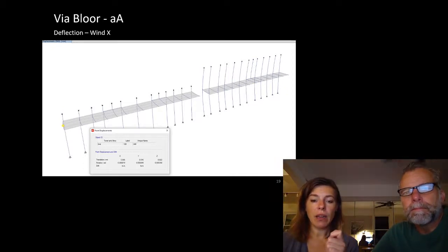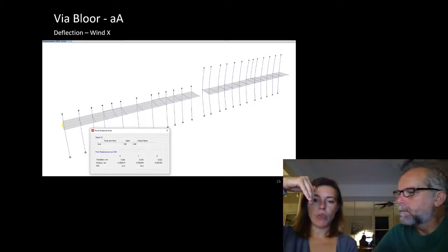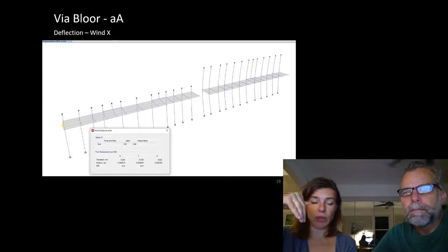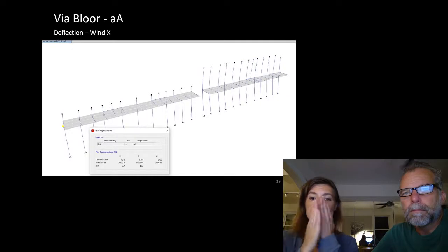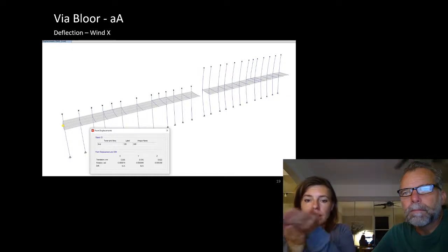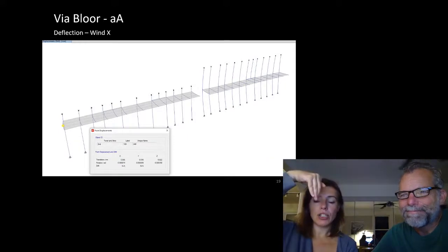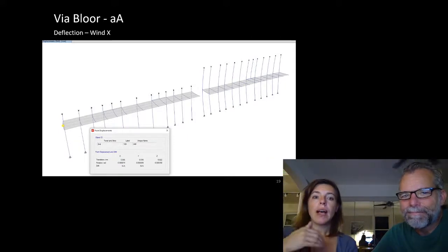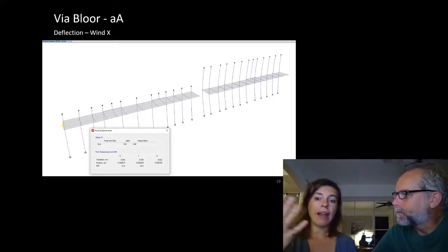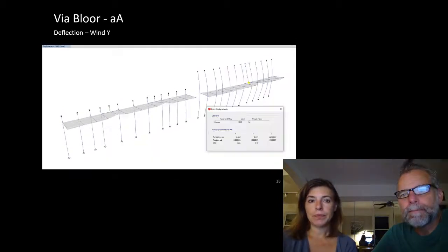So again, we needed the modification for compressive loads. We were worried about buckling because, again, they were showing just a thin plate. So instead we made a T. We made a T section. And once we needed that T section for gravity loads, it solved all of our racking problems as well.